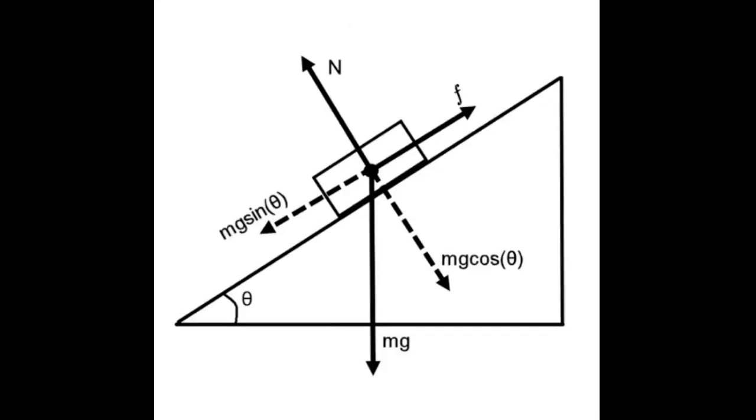In order to understand my experiment, I will first show you the free body diagram of the setup of my object. In my setup, I will have an inclined plane, and on this inclined plane, I will put a block. I will gradually start by increasing the angle, as you can see here, and I will increase the angle slowly until I can see the block just move, like a bit before it moves. And then I will record that angle, which will be my critical angle for this experiment.